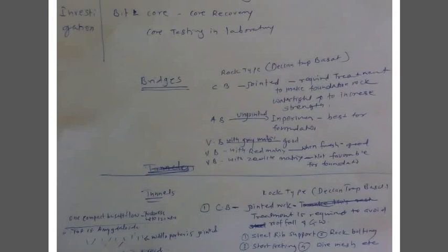Actually, amygdaloidal basalt is an unjointed rock, without joints. It is an impervious rock, therefore no treatment is required at the time of tunneling and after tunneling. So amygdaloidal basalt is known as the best friend of the civil engineer. Then tunneling in volcanic breccia is troublesome because the volcanic breccia with tachylytic matrix deteriorates on exposure to the atmosphere and creates problems. Therefore, the best way is to excavate the tunnel through amygdaloidal basalt.